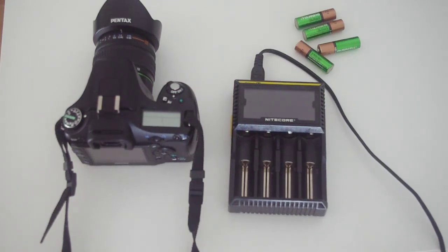Because typically nickel metal hydride cells have a lifespan of about 1000 cycles, so if you recharge them one time per 3 days, you will need about 10 years to fully wear out these cycles. So probably if you have dead cells you can revive them, but just don't use a quick charger.